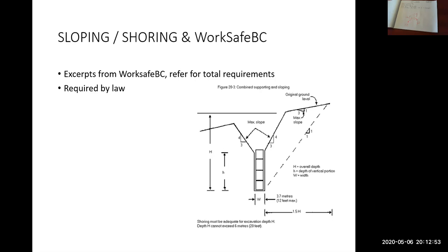So exercise 4, you were to calculate the cut and fill volume based on cross sections. So no, you weren't supposed to use any compaction factors there. So it's just a straight end area calculation. Further down into question 2, where it talks about how many tons of subbase, you were simply doing a conversion using the tons per cubic meter that I provided. So I said use 2.3 tons per cubic meter. So that's how much gravel you would purchase. So fill volume of cubic meters times 2.3.